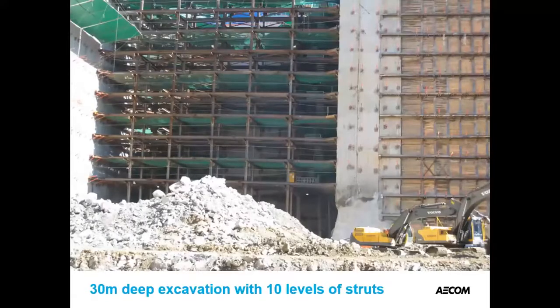But 4 years later, after the collapse in Singapore, so this is 2008, I was visiting a site in a nearby city in Southeast Asia with a 30-meter deep excavation, so that's the same. 10 levels of struts, that's the same. There's splays at the end of the struts going on to horizontal waling beams, which are the same, at least in this part of the site. Forget about the bit on the right, which has got a ping pile, and the bit on the left, which is anchored. But in this corner of the site, there's a substantial recess in a massive excavation, which has got very similar steel structural arrangement to what happened at Nicoll Highway.